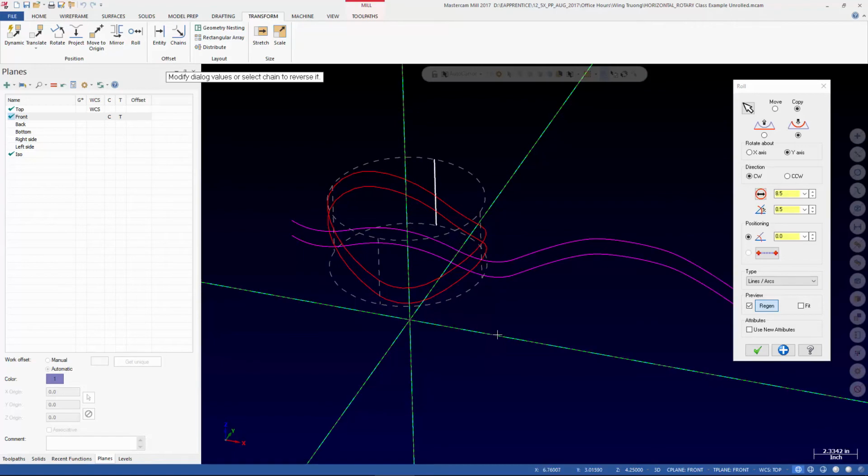So when you use the axis substitution toolpath, what you're doing is taking one of the linear dimensions and substituting it for an angle of rotation. So by default, you have to be on centerline with your tool, and you have to be at a constant radius. Now, you can put a taper.